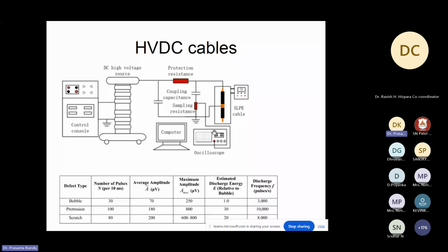Now since it is a DC voltage, we cannot put a blocking part here, because if you put an inductor, omega is 0, so it will be almost shorted, unless there is some ripple. We cannot put a capacitor for blocking as in previous cases, because it will not allow any power to flow. It will block it, because omega is 0, so the impedance will be infinity. So L will create a short circuit, it will not block anything, and the capacitor will block totally.